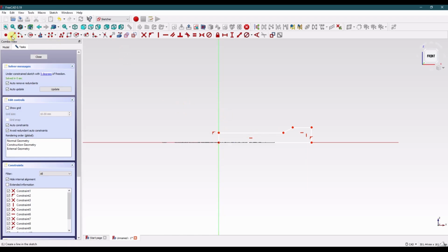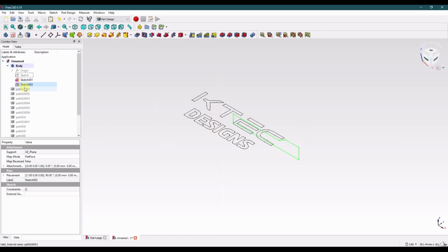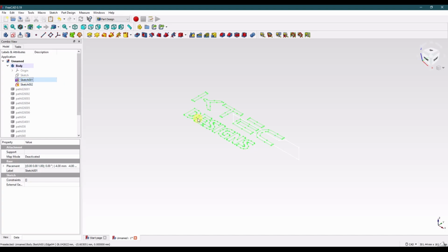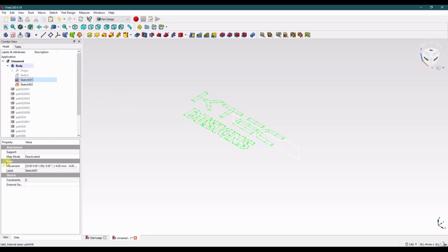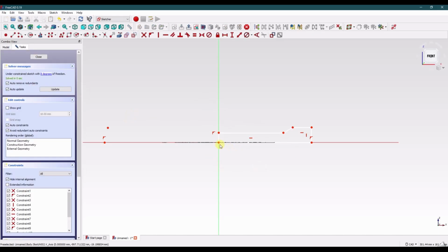All right. I'm going to create some symmetric points. You can see that the, I'll just close that for now. This sketch is on the top plane and I'm modeling this where the bottom of the object is on the top plane. That's okay. We can change the position. Well, I should be able to change position. I can't change attachment on this one, can I? Yeah. So actually, we need to move this down.